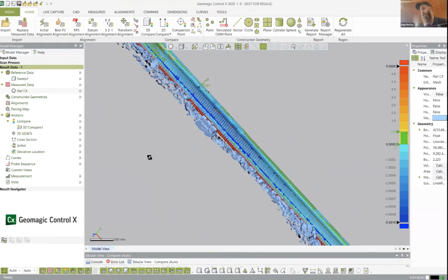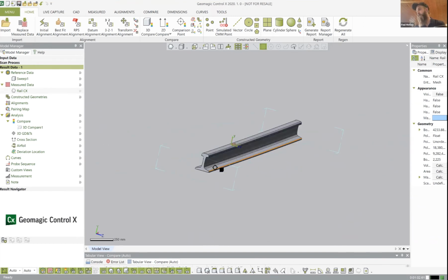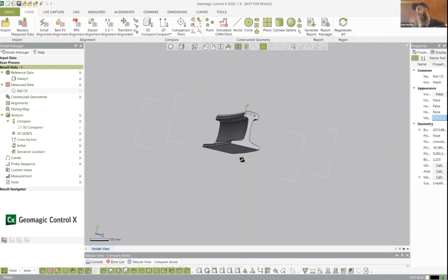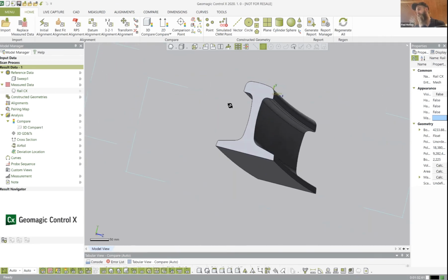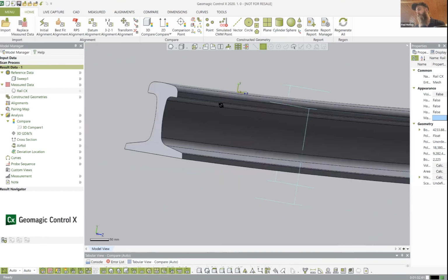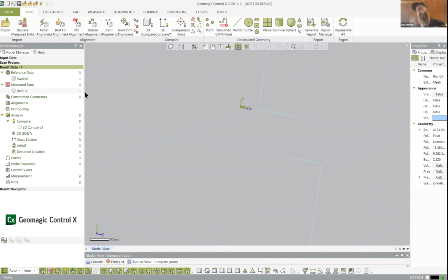So this is another section of a rail that we did the exact same process with. So we scanned it, uploaded it to the cloud, processed everything. The only difference is instead of downloading this onto an iPad, I went ahead and downloaded this onto my standard work computer and built out a rail section using SOLIDWORKS. So we did a more traditional rail section. This one I actually swept the curve of the known rail into. I think you can kind of see that there. So for this, the purpose of this particular process was to take our scan data, where we can see here.